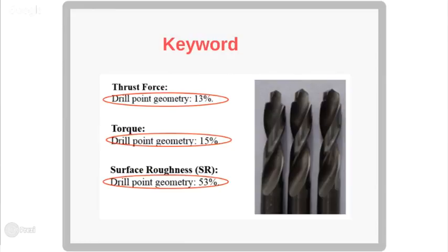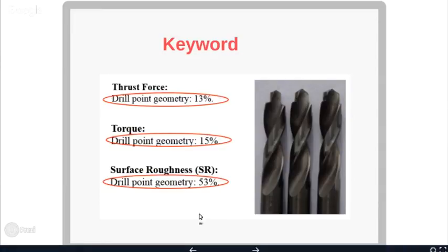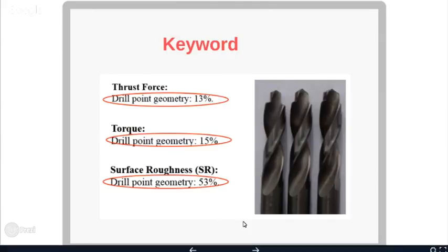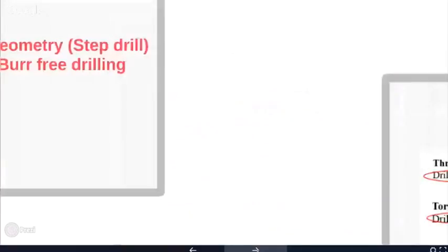So it motivated me to carry out the research particularly on this drill point geometry, that is step drill. My second phase of experiment starts with the drill point geometry. And one more thing we observed from this one, the burr formation is minimum in the case of step drill point geometry.